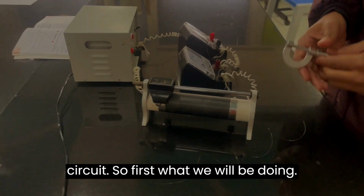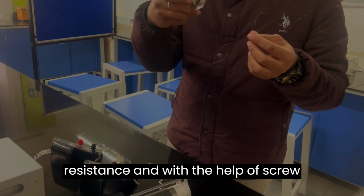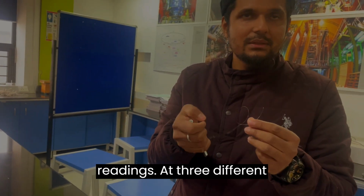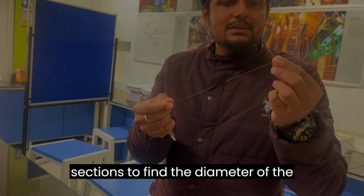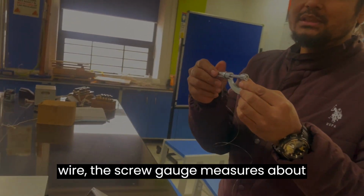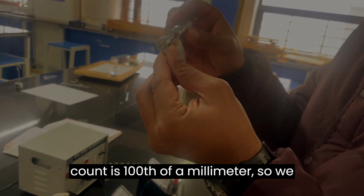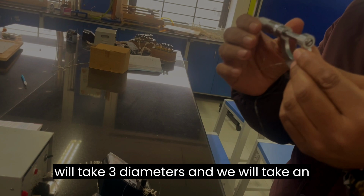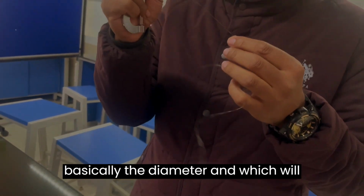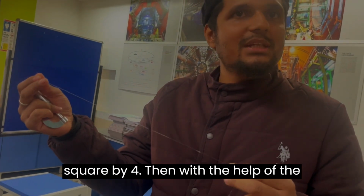So first what we will be doing, we'll be taking the wire of an unknown resistance, and with the help of screw gauge we are going to take 3 readings at 3 different sections to find the diameter of the wire. The screw gauge measures about 1/100th of a millimeter. Its least count is 1/100th of a millimeter. So we'll take 3 diameters and we'll take an average of it. So we are getting basically the diameter, which will eventually give us the area, pi d square by 4.